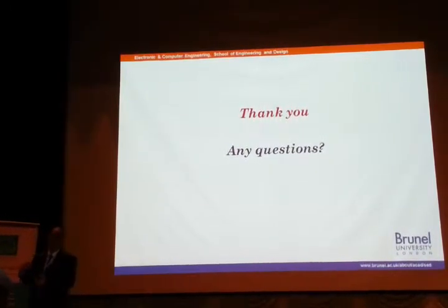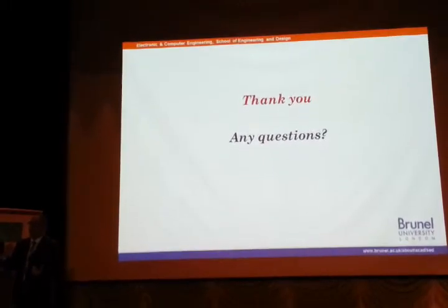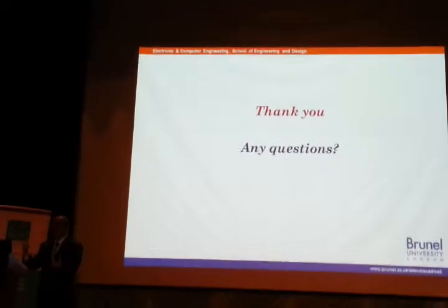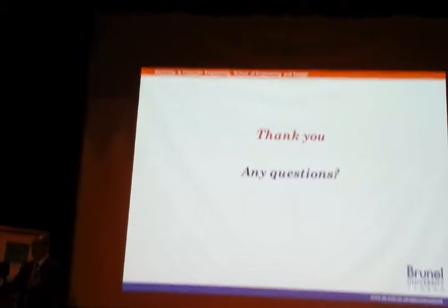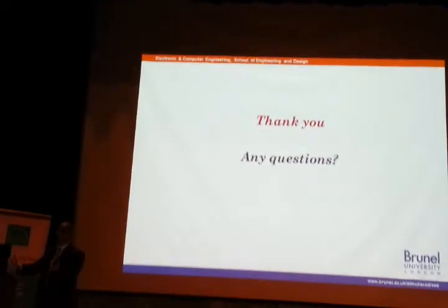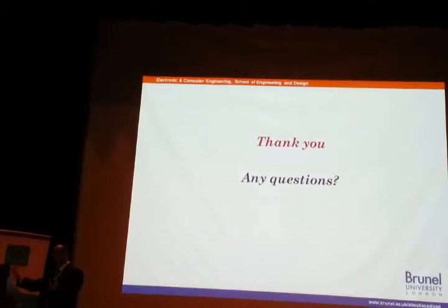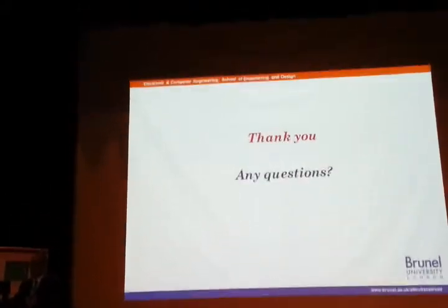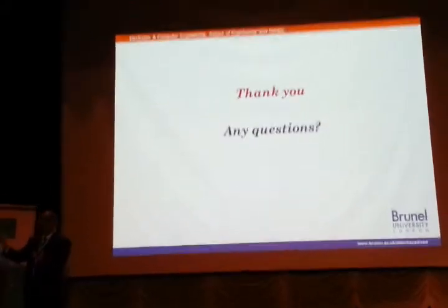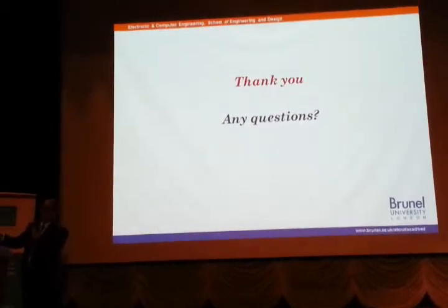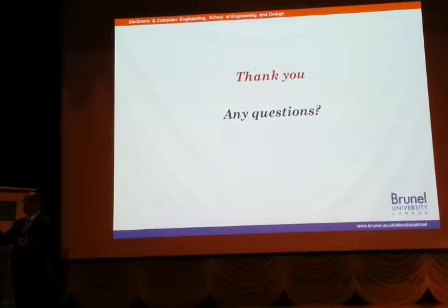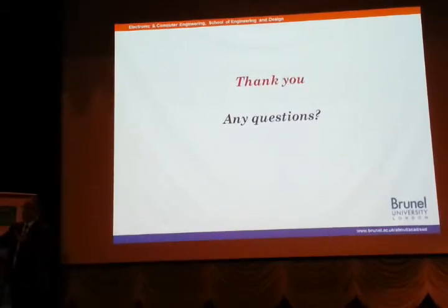Actually, he is trying to operate an active filter, very similar to one of the questions there. For example, if I operate the inverter at high switching frequency, that means a lot of losses, or the filter. Why not try to find an optimization between both of them, i.e., push the frequency to a specific point and put the filter to a specific point where I can find the optimal cost and efficiency-wise as well?